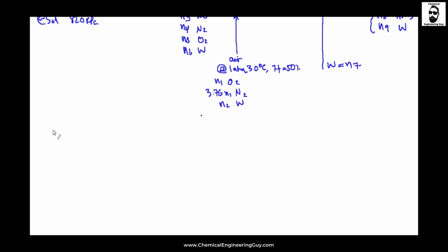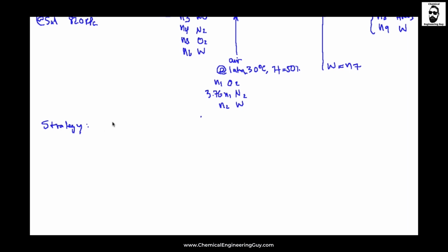We're going to start with the strategy. So the strategy is as follows. We need the temperature of saturation. That's good because we know it's saturated here. So with this, what does that mean? It means that in saturation we can calculate the temperature by using the Antoine equation. So we'll need the constants A, B, and C, and then we get T of saturation.